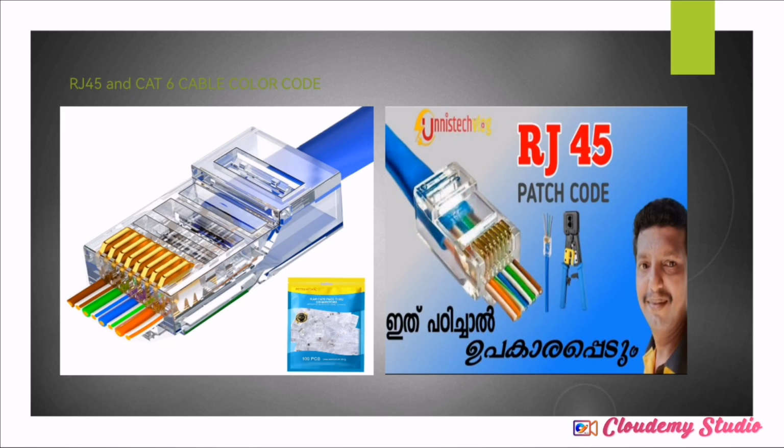But some other clips or RJ45s don't come out here, they don't pass through, they remain there. But it's your job to make sure that all these colors have reached the end, even if they didn't protrude here. Then you clip, making sure these terminals go inside and hold these. Then you test this side and the other side, and you find that the cable is working fine.